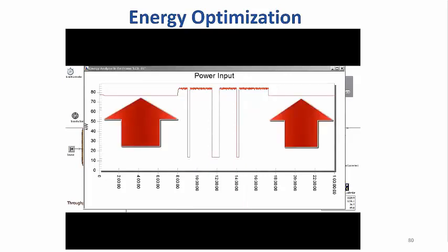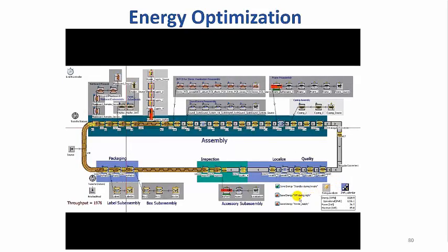After looking at this chart, you may have guessed that we could save even more energy by switching to the off state during off shift or unplanned time, instead of leaving everything in the operational state. Since these periods are long, we are switching to off state instead of standby for even more energy savings. To do that in our model, all you have to do is check the on-screen Save Energy Off During Night checkbox. Now, after running our model for one day, our Energy Analyzer's display panel shows that we've decreased total power consumption from 1,820.9 kilowatt hours to 819.1 kilowatt hours.